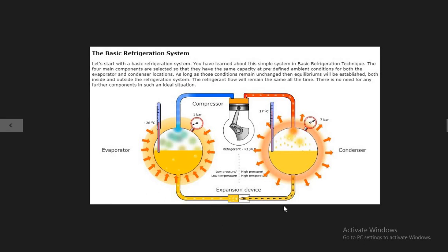These are so simple. But the main intelligence applies in the design and understanding of the condenser and evaporator. So each time you are going ahead to buy a system, you need to first think of these complicated equipments which are connected. And the interesting fact is that both of the equipments which are connected here are actually the same. I mean, they are heat exchangers doing different jobs. Here in this heat exchanger, condensation is happening, and in the other heat exchanger, there is evaporation happening.